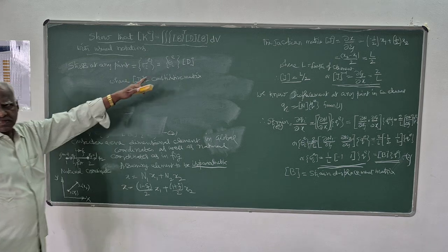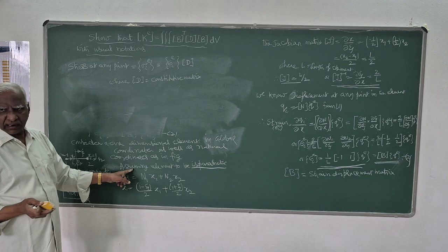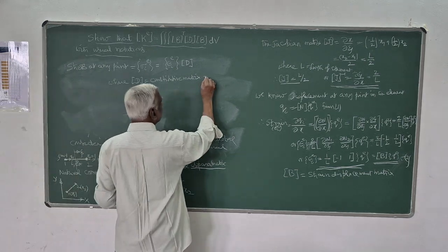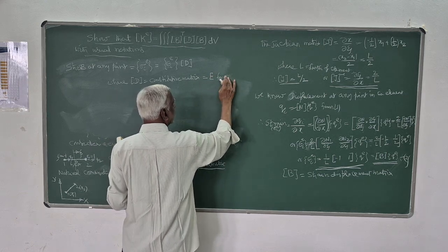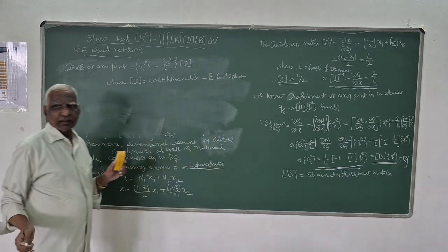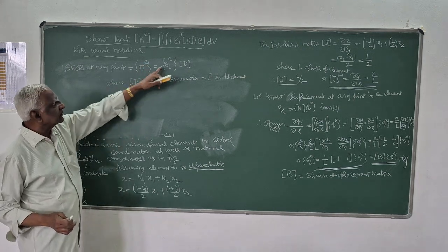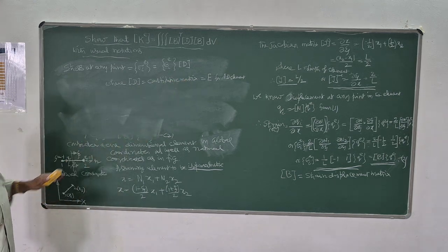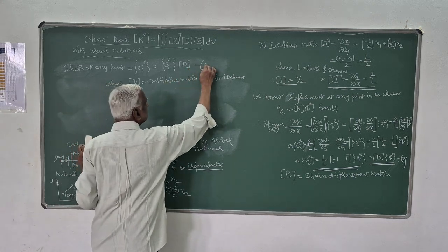This is from elasticity. It is nothing but the stress-strain relationship. Of course, in the one-dimensional element case, D is E, Young's modulus of elasticity, equal to E for a 1D element. It is the relationship between stress and strain, which is called the constitutive matrix. Of course, for a one-dimensional element it is E.